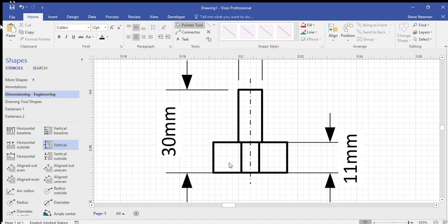Alright, now having a look back at our drawing tool down here and our flywheel. I want to machine our flywheel next, so you guys can picture that this part here has been put into the chuck, and our aluminium flywheel is the part that's spinning around. Now, the problem is here, just before, let's change some lines here to make it make more sense. If this part's the big aluminium flywheel, then you shouldn't be able to see these two lines.